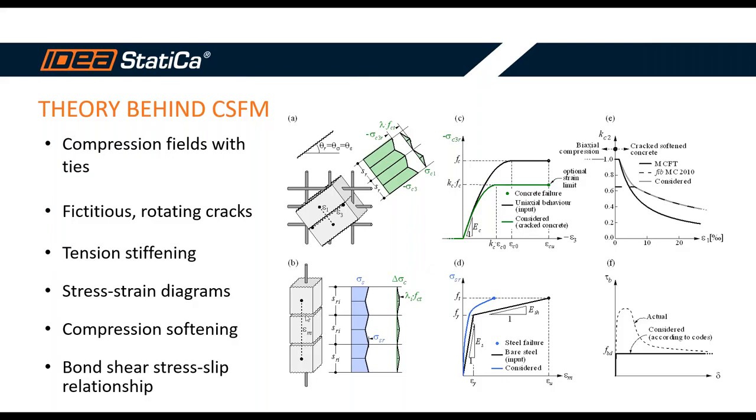So we have a crack, and due to the equilibrium, we can calculate average strains. The model considers maximum concrete and reinforcement stresses. So we have reinforcement stresses and concrete stresses, while we are neglecting concrete in tension, except for tension stiffening effect.